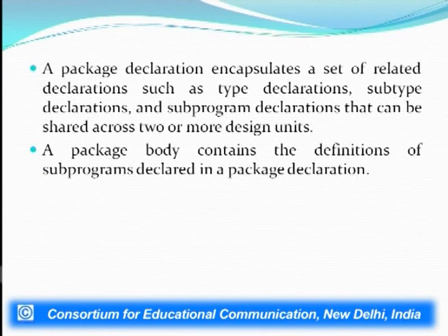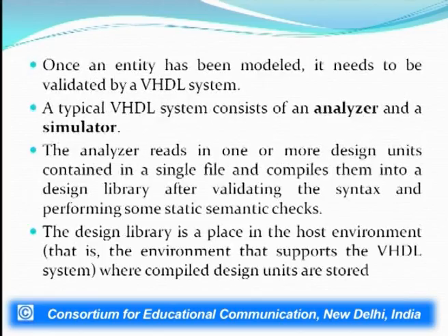Further, a package declaration will be encapsulating a set of related declarations such as type declarations, subtype declarations and subprogram declarations that can be shared across two or more design units. And a package body contains the definitions of the subprograms that are declared in the package declaration. So every package declaration must have a package body wherein the declarations have been elaborated upon.